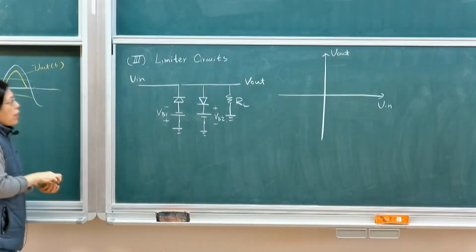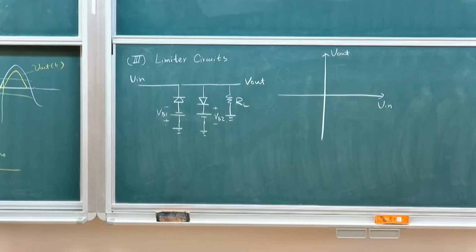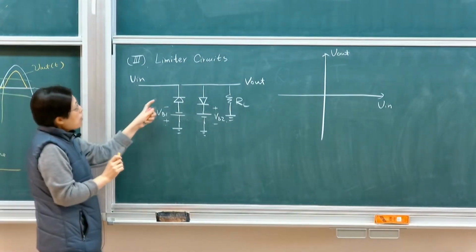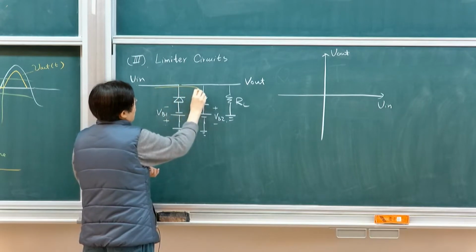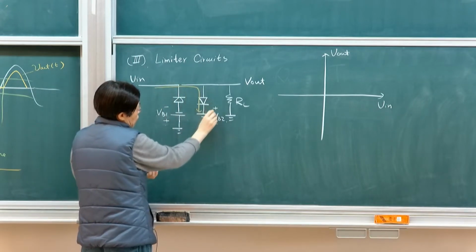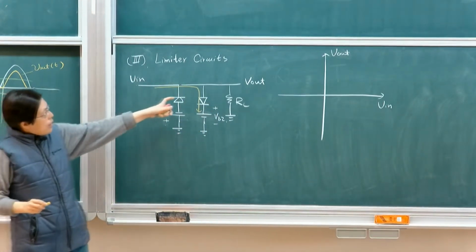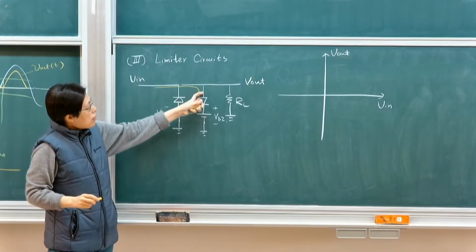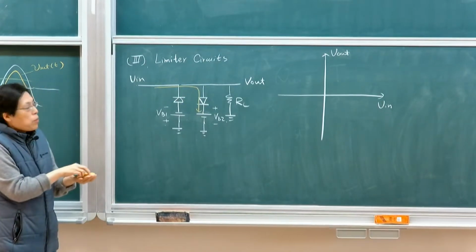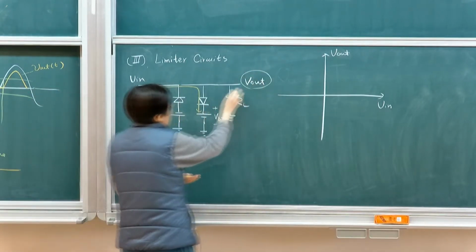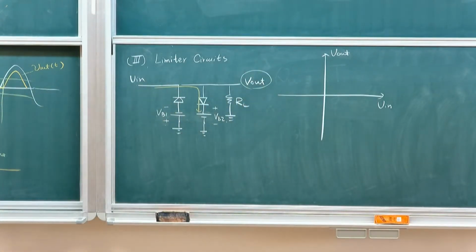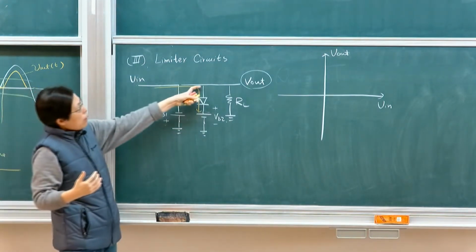what basically happens is that if I give you a very high positive voltage, it would then have all the current going through here if this turns on. Once it takes the current, it will be clamping the voltage. We'll call it clamping of voltage, meaning that it would allow the voltage to be clamped at a particular level.